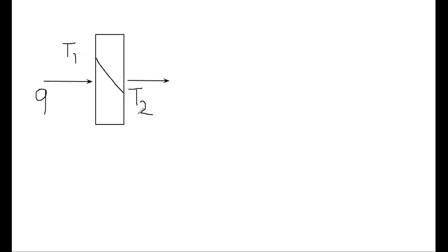Alright, now again let us say the thickness is dx. The thickness of the wall being dx. So, from Fourier law of heat conduction, Q is equal to minus K A, or let us set the temperature difference T1 minus T2 is dT, K A dT by dx.